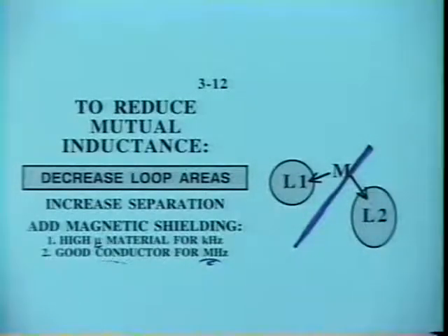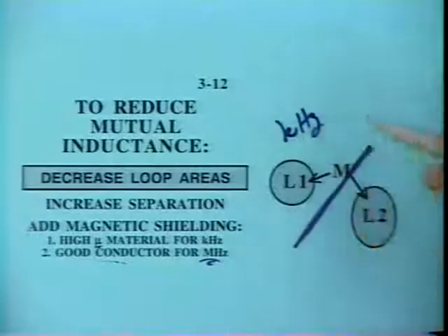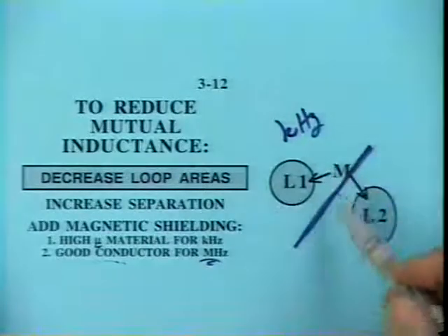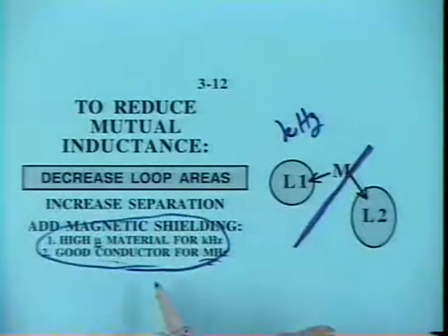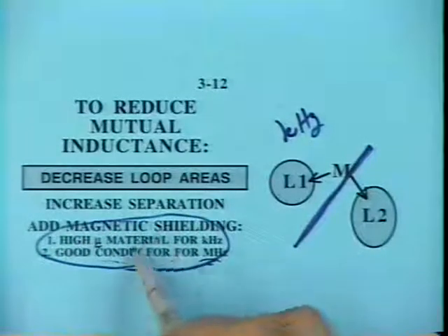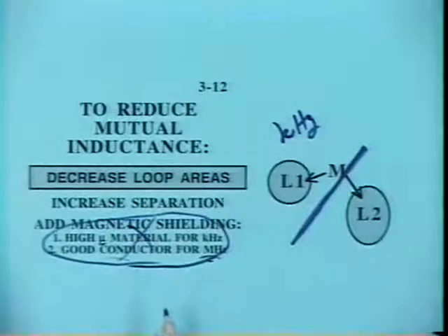We'll show all of this in a later session about how to employ magnetic shielding. But if the problem were in the kilohertz range, then it's going to be a very tough solution because we're going to have to use an expensive material that might only give us a few dB of noise reduction. So I wouldn't put my first attempt at solving the problem on the magnetic shielding. I would save that to last, basically a desperation effort probably.